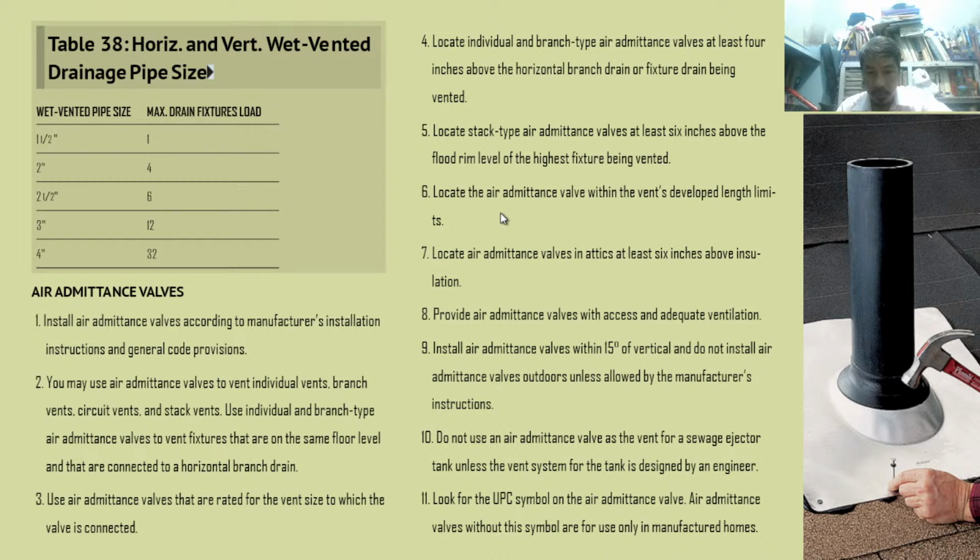Do not choose an air admittance valve as the vent for a sewage ejector tank, unless the vent system for the tank is designed by an engineer. So for venting a sewage ejector tank, do not choose an admittance valve unless it is designed by an engineer.